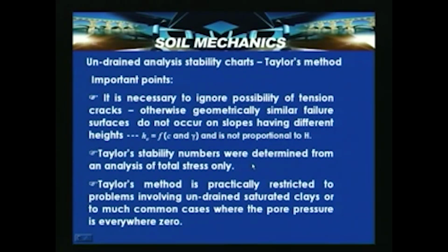Though some attempts have been made for using it for effective stress, in such situations it leads to serious errors. In such situations, Taylor's method is practically recommended or restricted to problems involving undrained saturated clays, or to cases where the pore pressure is everywhere 0.